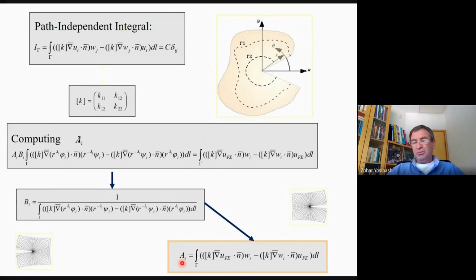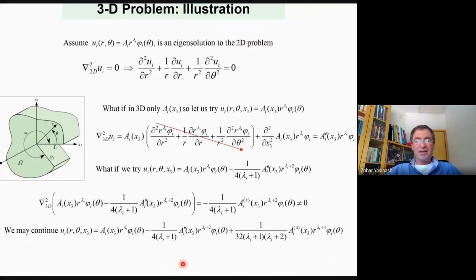And I can compute each and every one of them independent of the other, because each time I will choose a different dual solution here, I will get a different coefficient here. And that's the way, a very simple and very accurate method for us to extract stress intensity factors for the Laplace equation, and then we can do that for the elasticity equation.